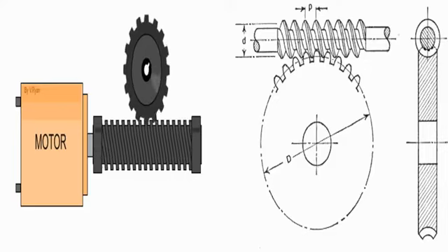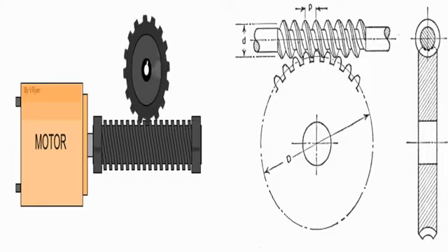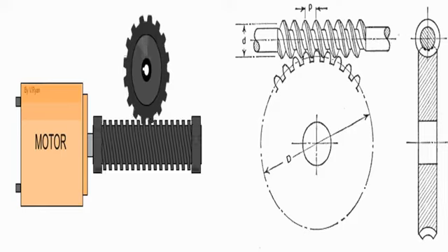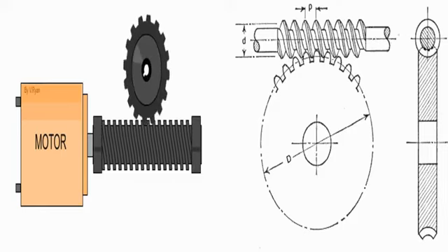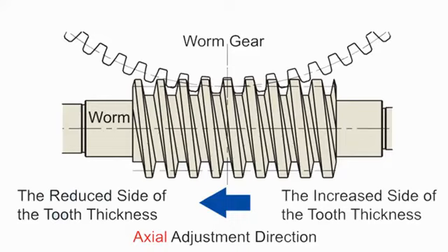One of the major advantages of worm gear drive units are that they can transfer motion in 90 degrees. Worm drives are used in presses, rolling mills, conveying engineering, mining industry machines, on-runners, and worm drive saws. In addition, milling heads and rotary tables are positioned using high-precision duplex worm drives with adjustable backlash. Worm gears are used on many lift, elevator and escalator drive applications due to their compact size and the non-reversibility of the gear.